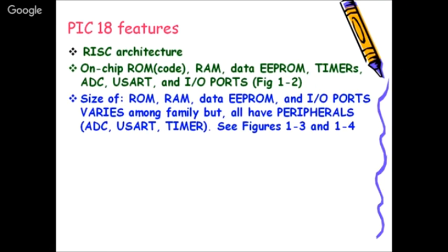And of course, on-chip code memory is available up to 128 kilobytes in case of PIC 18, but it has a scalability up to 2 megabytes. And when it comes to developing embedded systems, this matters, that how much memory we can connect to the particular controller, unlike your general purpose x86 based embedded system, wherein you have all the flexibility of adding as many blocks as you want. But in case of select microcontrollers, you have limitations that once you select, it remains fixed. So if you select a PIC 18 family, your ROM can go up to 2 megabytes.